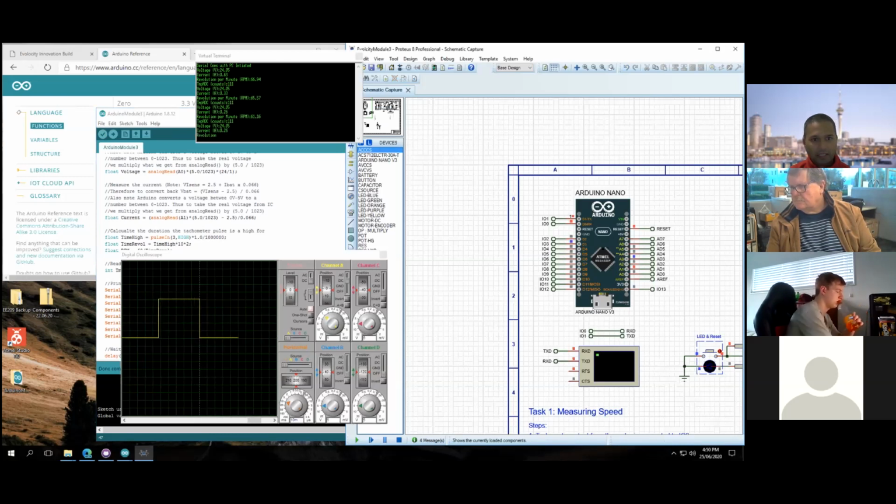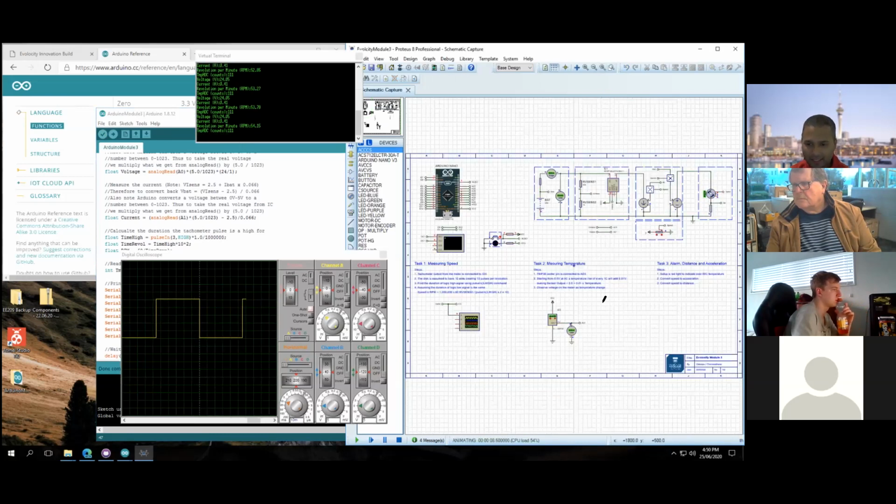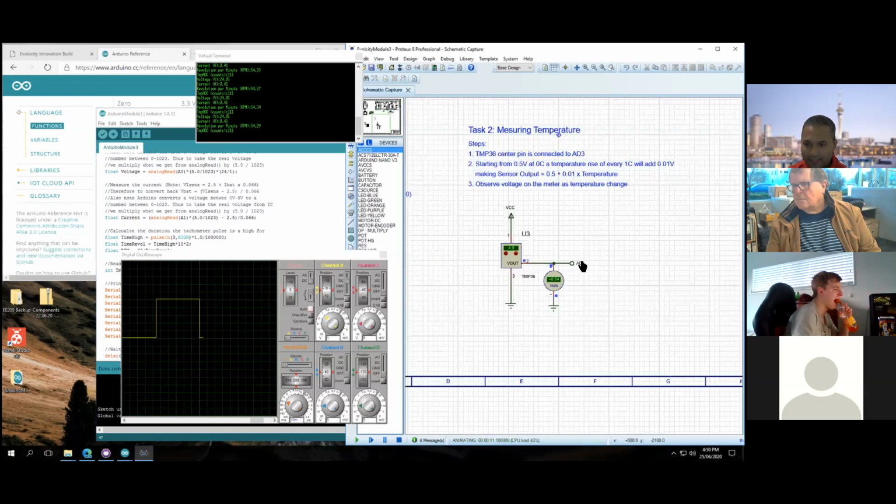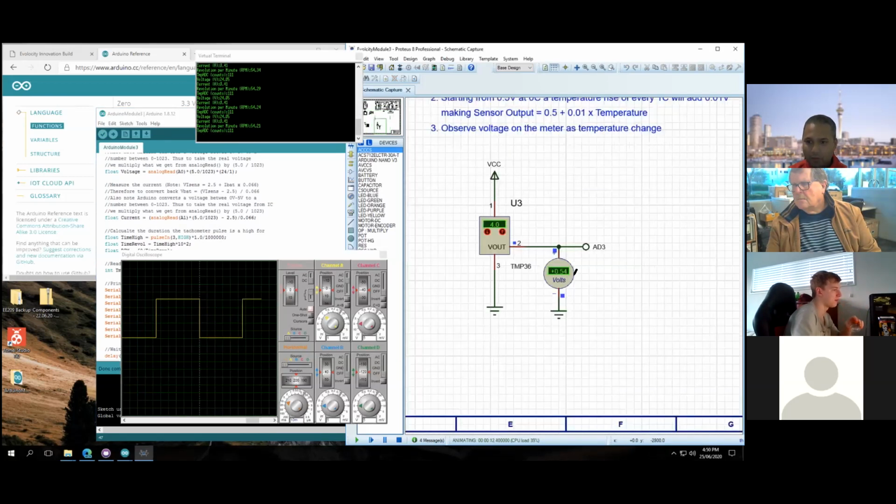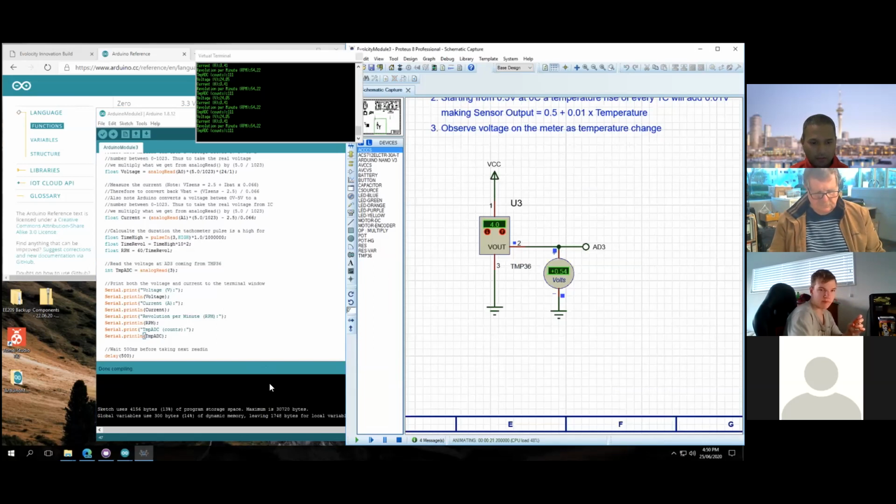Right, it's showing me 111 as the count coming from the analog to digital converter, which we learned last time. And if you look at the voltage, it shows as 0.54 volts at that point, which means it's 4 degrees because 0 degrees is 0.5 volts and every degree is 0.01 of a volt. Now, I'm going to close this so we can see a bit of things.